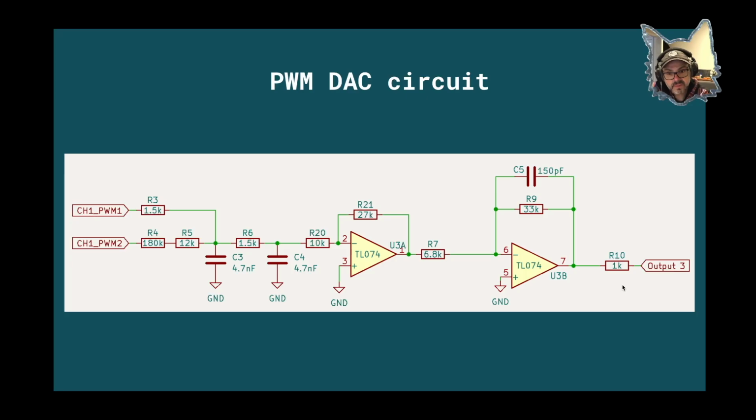If you want a signal that is centered around the 0 volts, adding a positive voltage right at this point will shift the signal. The signal right here is in the positive side, but over here we invert it. So over here the signal is inverted and it's negative. So if you add a positive voltage, you're gonna bring it closer to 0 volts. So when you flip it again, it's gonna end up back in the positive here. So that's one way you could do it. I'll leave it up to you to see how it's best suited for your application, but these are the things that you can tweak.